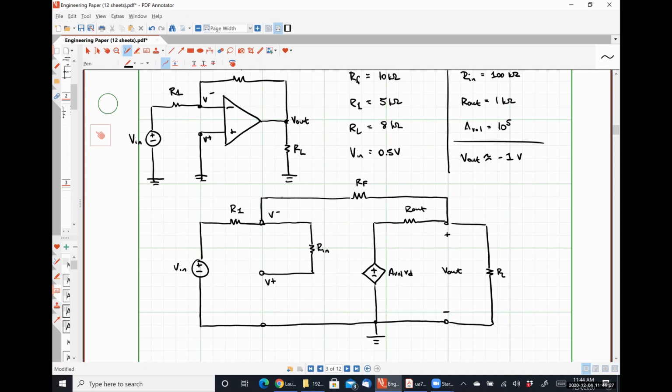Everybody okay? All right, so what's the last thing that I need to do? Well, I need to connect my non-inverting input terminal to ground. So, done. So in this case, flipping those input terminals, so to be clear here, this is my differential voltage VD.